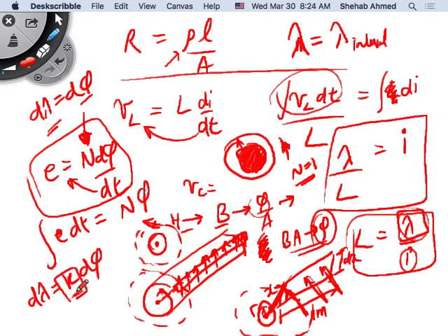This constant k is less than 1, because obviously when you're linking the full conductor, it's 1. So this portion is less than 1. It depends on the ratio of the area that you are currently integrating up to and the full area of the conductor. So we said it's x over r squared, right? Because the area is pi x squared over pi r squared, so the pi goes with the pi, and we end up with x over r squared.